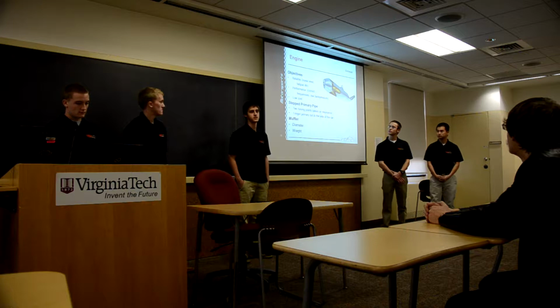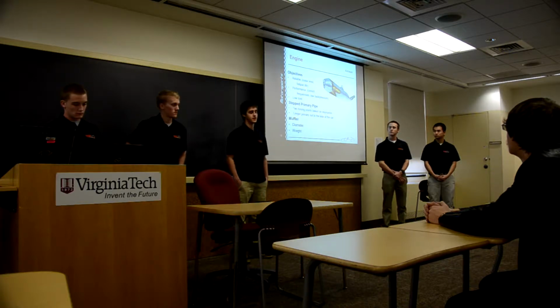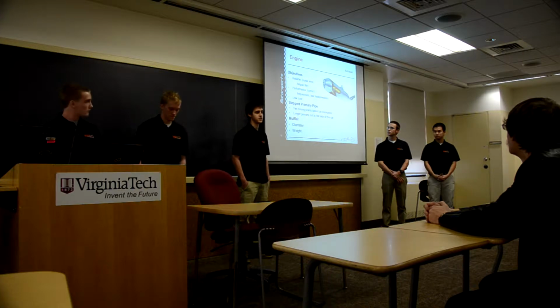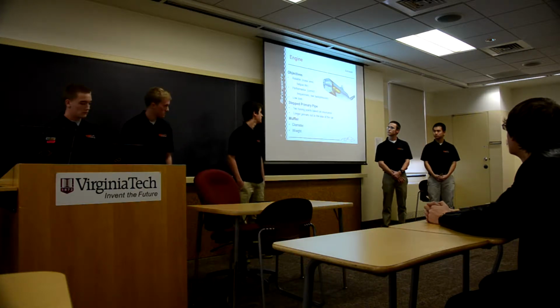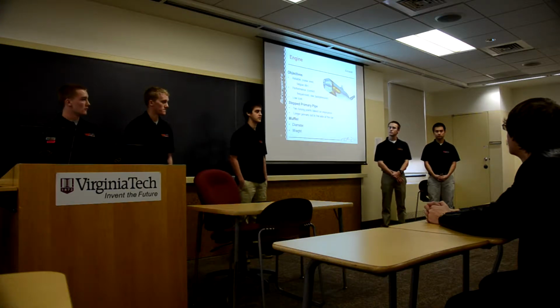An objective of the engine exhaust is to make sure that it's reliable. This means that the car needs to be under the required decibel level of 100. It also needs to have a strong fatigue life. I need to make sure that cracking does not occur in the muffler due to vibrations and stresses caused from mounting it. I also need to make sure that it has the correct frequencies to make sure that it has a low back pressure, which will allow for more exhaust gases to come out.